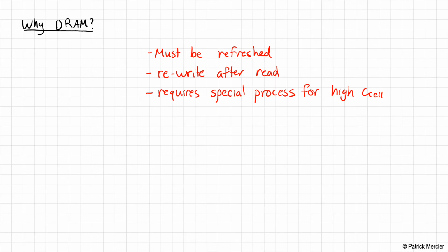And so what they typically do is they have a process in some CMOS technologies called a deep trench capacitor. Effectively, if you look at the gate of your MOSFET, maybe it looks something like this. It's implemented in CMOS. We have a doped region here, N+. What they typically do is they have this extra large doped area here, where they put a dielectric in the middle, which basically allows them to create a very large capacitor.